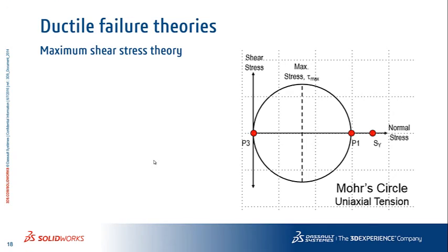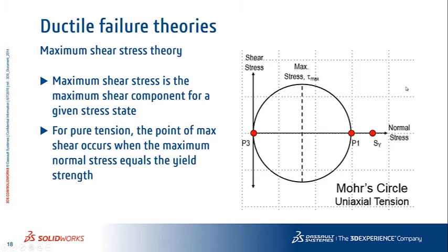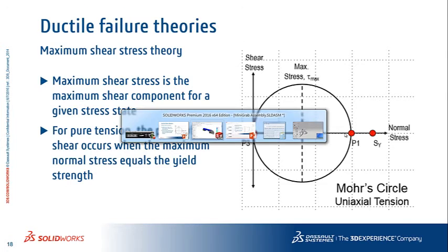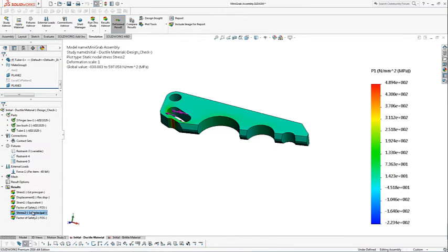All right. Now the third criteria is the maximum shear stress theory. And the maximum shear stress theory again requires us to go to a Mohr circle and calculate what the maximum shear stress component is going to be, and then we can relate that. If that is larger than 1/2 of the yield strength of the material, that's when we know yield is going to start. Now, there are ways for us to go back and look at the different shear states.